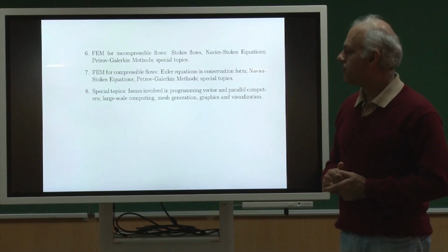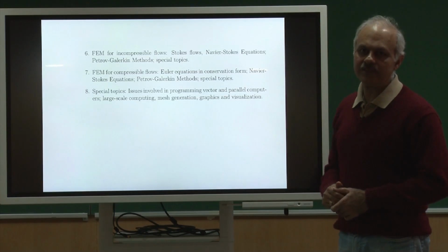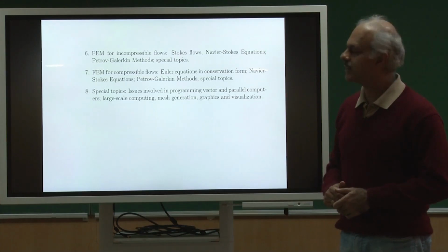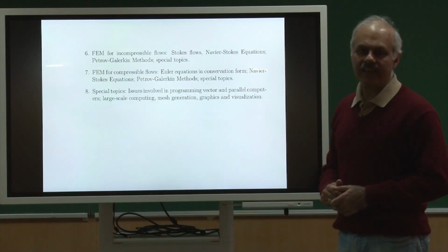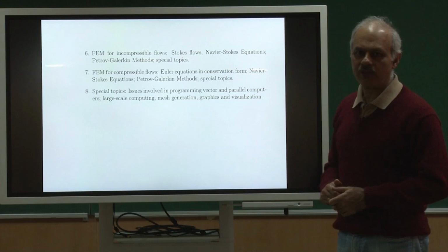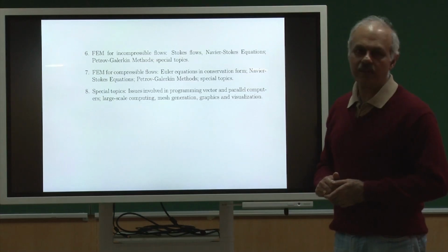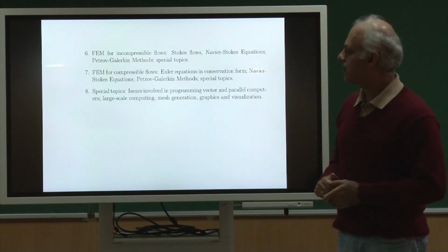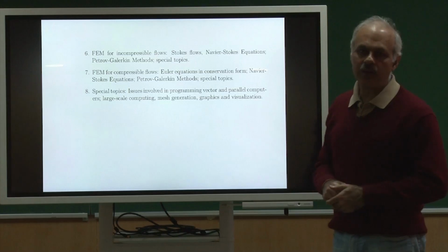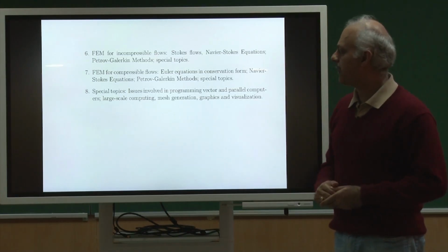Those of you who are familiar with upwinding in finite difference methods will realize that if you use a staggered grid for solving your equations, that works better than grids where the pressure and velocity are not staggered. These kinds of methods allow us to do similar things in the framework of finite elements.